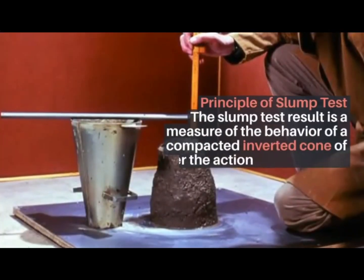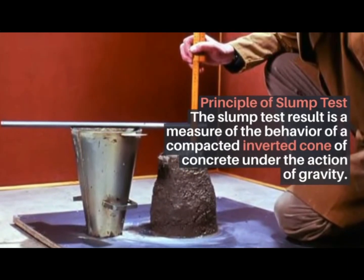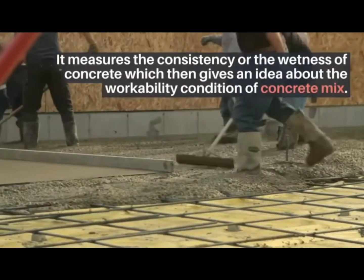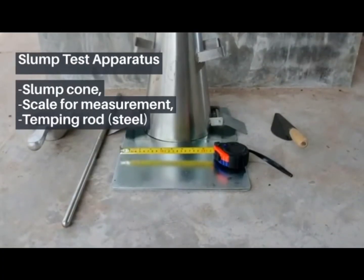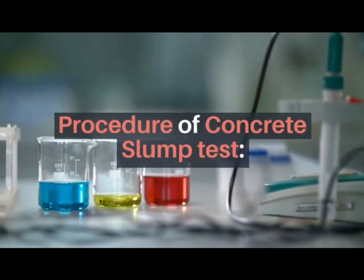Principle of slump test. The slump test result is a measure of the behavior of a compacted inverted cone of concrete under the action of gravity. It measures the consistency or the wetness of concrete, which then gives an idea about the workability condition of the concrete mix. Slump test apparatus: slump cone, scale for measurement, tamping rod, steel. Procedure of concrete slump test.